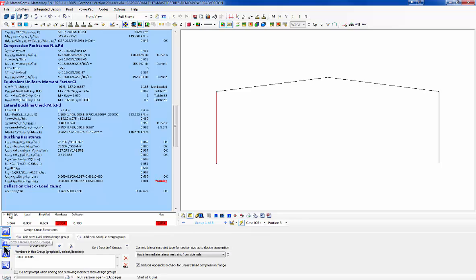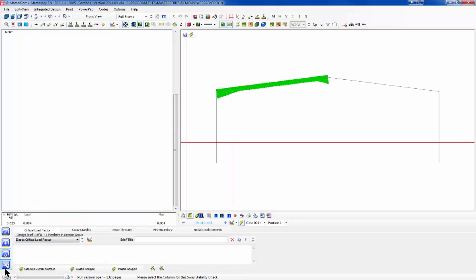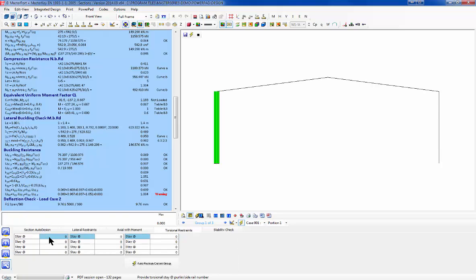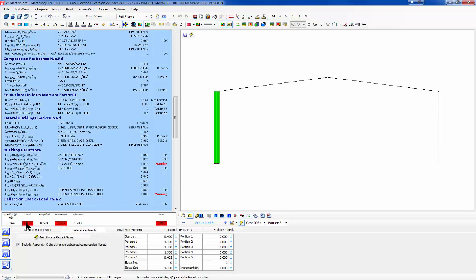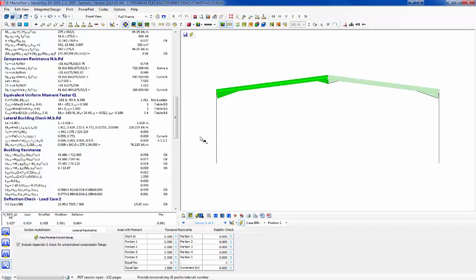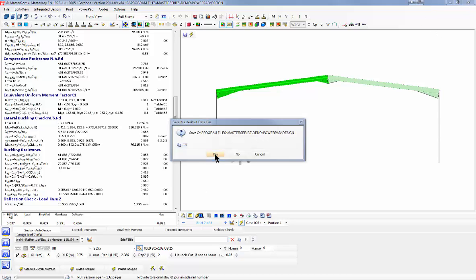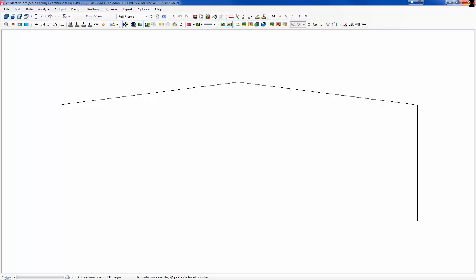So now what's it telling us? It's telling us that everything works fine, we just need to restrain our members. So I can come in and do an auto restrain on that current member, and it's automatically tried to restrain it up. But I think I have overcooked my books a wee bit here on this frame. There are separate webinars on Masterport. Like all the other programs, obviously we're just giving you a glimpse of what is in PowerPad. Okay, that's the integrated programs.